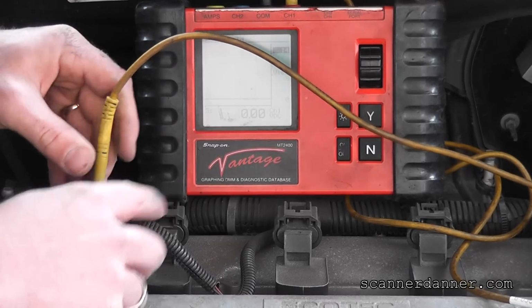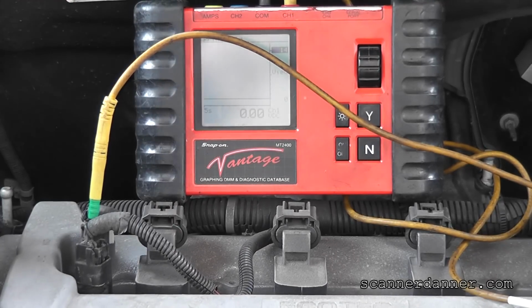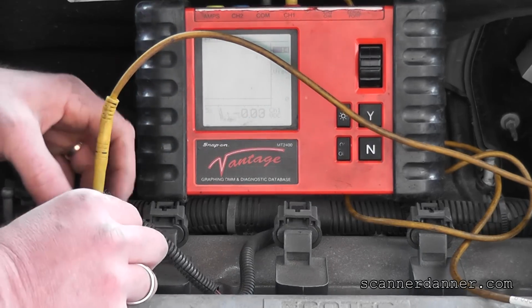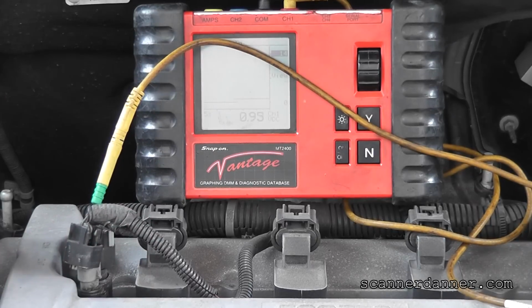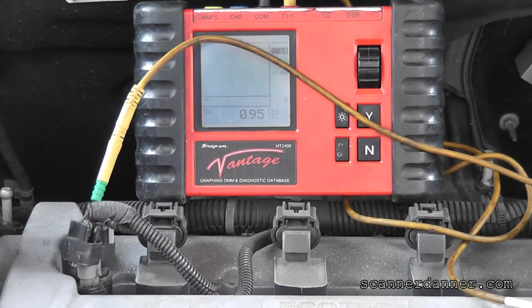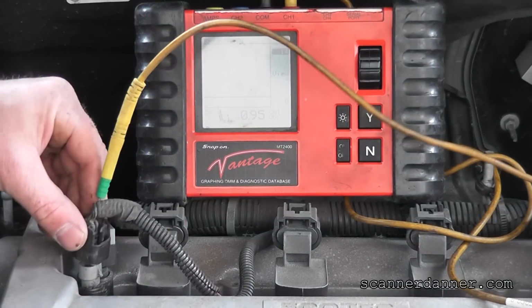All right, so this is going to be the intake solenoid unplug test. I'll bet you we see the same 0.93 of a volt. There's that 0.9395 of a volt bias, proving what I just said. This exhaust solenoid is definitely open.